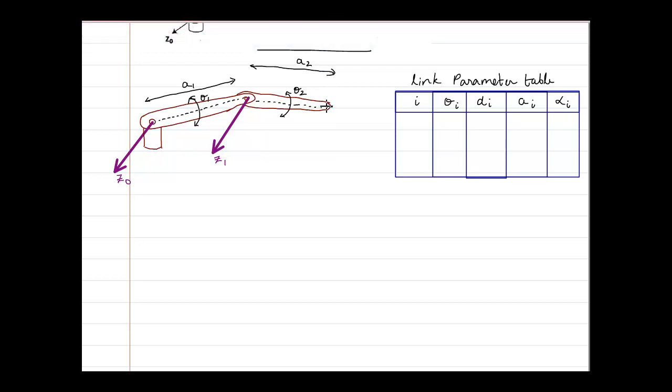Now where should I draw it? Should I draw it in the front or in the side? Basically we know that the rule is, for the end effector, try to draw the z axis exactly as the previous joint. The previous joint is drawn in this direction, so I will draw this one again in this direction, which is parallel to z1. So this now becomes zh.